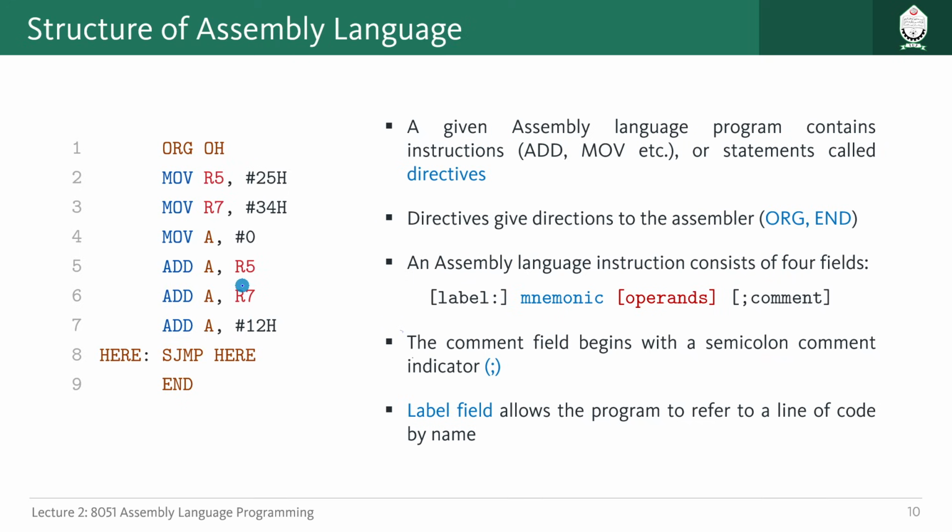That's why we have this assembler directive. This line will never be converted into code and saved onto the ROM. Rather, it will just command the assembler that afterwards, whatever you see, you should start storing from 0000H location, or at least make machine code that will do that. Okay, so that's how it works.